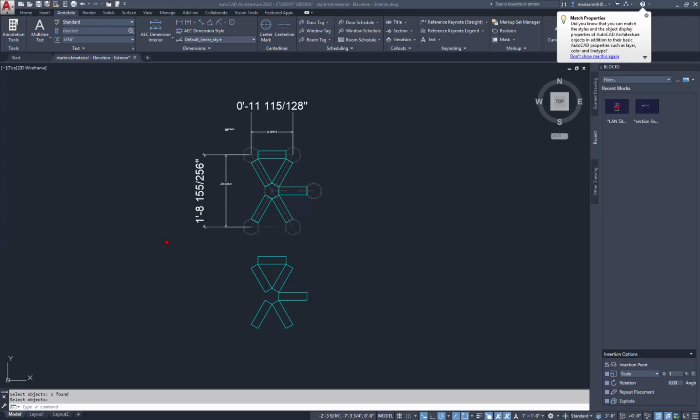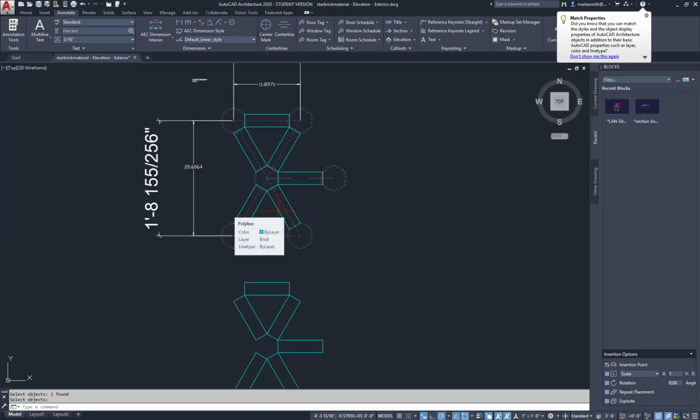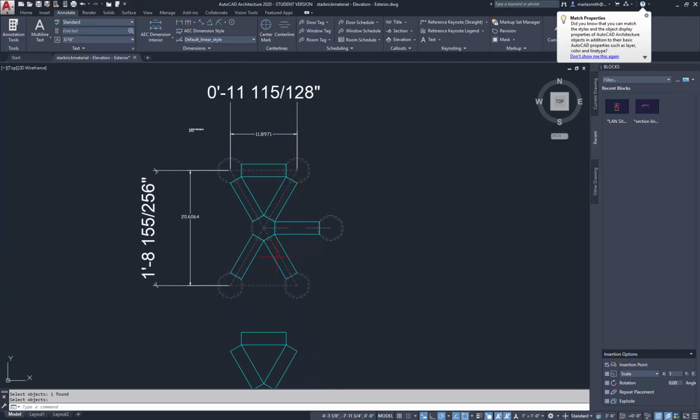Hey Michaela, I finally had a little time to come in and finish this guy up, and I just wanted to show you the pattern. It's an equilateral triangle, which you probably knew already, but the proportions that you'll need with the brick that you're using, the 8 inch by 2 1/4 inch, are these proportions. So you'll need to set your divisions on your wall to fit these. But basically, the component has a point here, here, here, and here, and these bricks are glued to it.